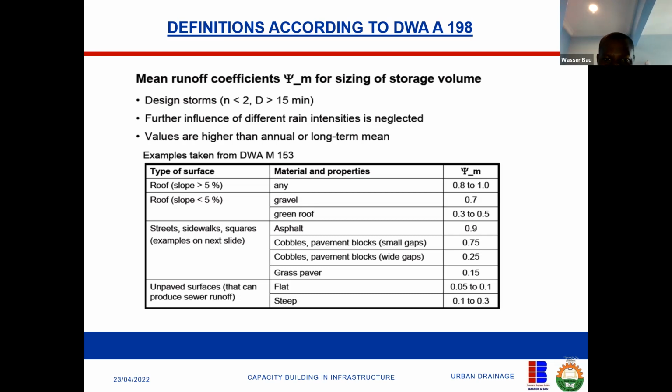If you want to pick a value for your rainfall intensity, you don't just pick any value. It depends on what you're designing for. You don't just decide on your own to pick a 5-year value, 10-year value, 15-year value, or 25-year value. No. If you are designing for a place that has high insurance value, let's say a city center, I'll use a very high return period.